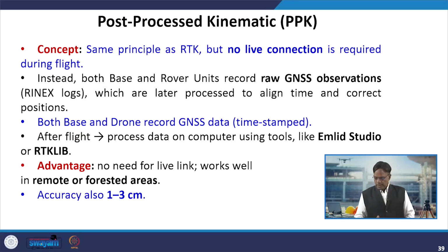But there is another technique which is called the PPK technique, and the PPK technique basically is the post process kinematic technique, and the concept is the same principle as RTK, but no live collection is required here. We will collect the data, and after collecting the data we will process the data through software like Emlid Studio or RTKLIB, software which can be used for processing this data.